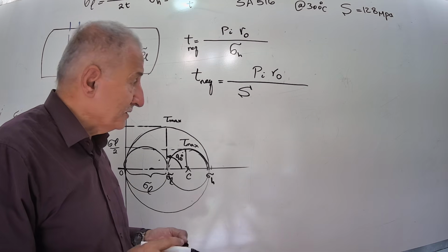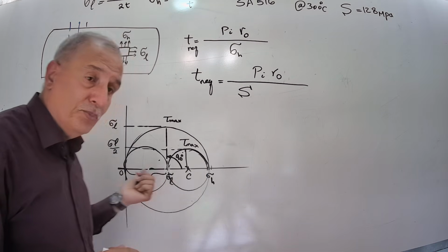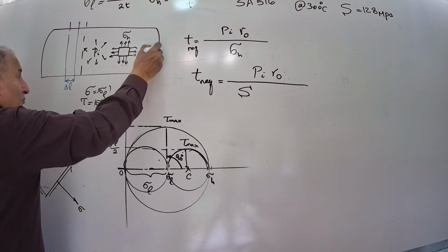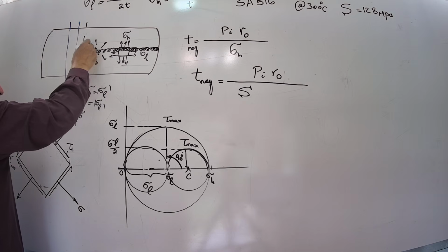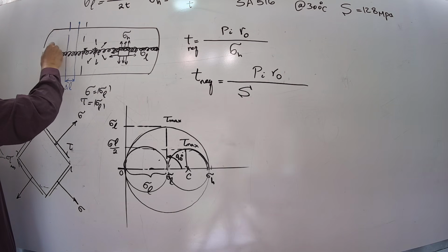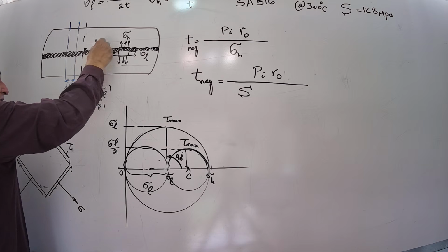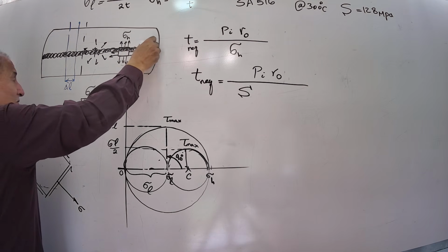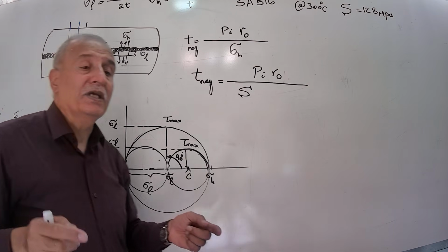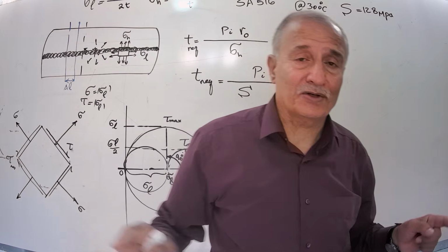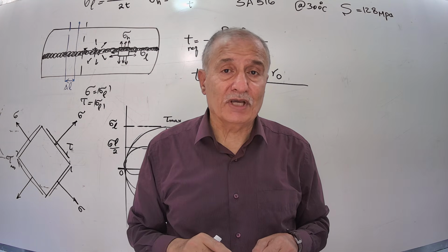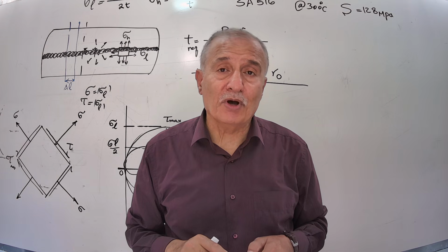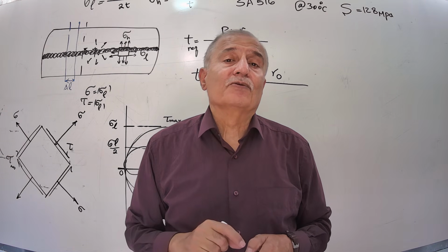But the problem is this. They weld after rolling the plate, they weld it at seams, longitudinal seam here. And if it is completely X-rayed, fully X-rayed, completely radiograph, full radiographic X-ray, you can say, okay, I'm sure about the weld,